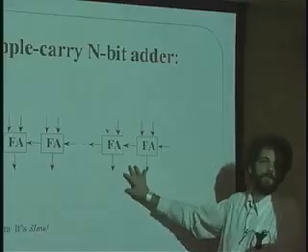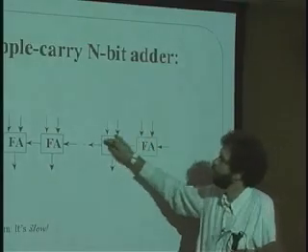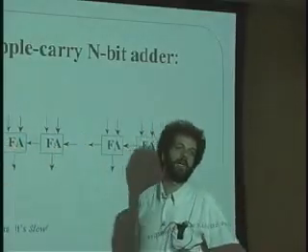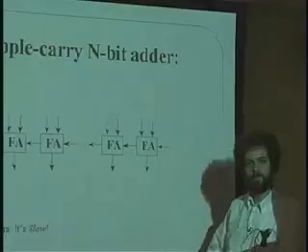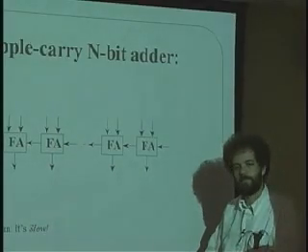Not for these least significant bits. Those get figured out pretty quickly, but it takes a long time for the carries to ripple all the way through here until they finally get to the end and pop out. That's in the worst case. That's in the worst case, yes. Best case, you're not taking much.